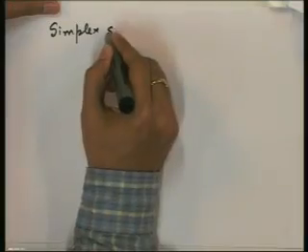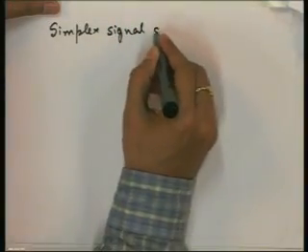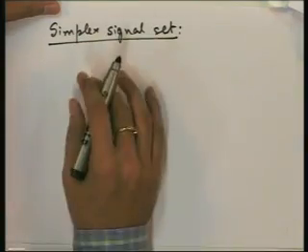We have just now seen, before discussing this, that if you have an orthogonal signal set of dimension 2, we can bring it, by translation and rotation, to a signal set in one dimension. Similarly, a 3-dimensional orthogonal signal set can be brought by translation to a 2-dimensional signal set. So, now we will generalize that concept, and that kind of signal set is called the simplex signal set.